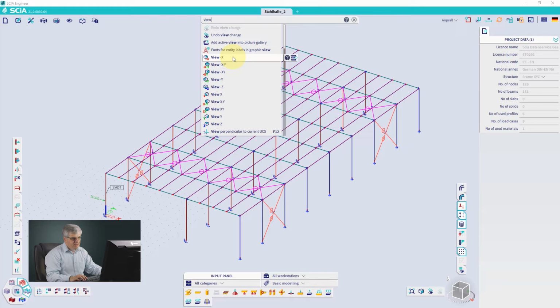You can create shortcuts. For example, I very often during presentations have to change the view from top to front, left side and so on, axonometry, from axial to shaded model, to volume model. So I have some commands defined, for example, view from the front side. This is view in Y direction. Where is it? This is simply 1. So you don't need to create shortcuts with Control or Alt. You can use some letter of your keyboard. For example, from the left side is 2.